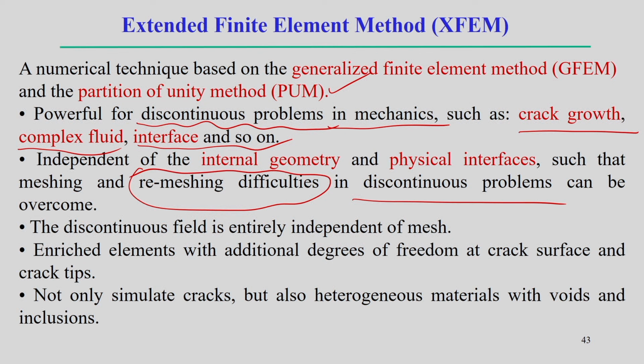So, this discontinuous field is entirely independent of the mesh, that is very true, and enriched elements with additional degrees of freedom at the crack surface or crack tips may be required. So, some sort of enriched elements has to be developed. We have to understand what the enriched elements are.